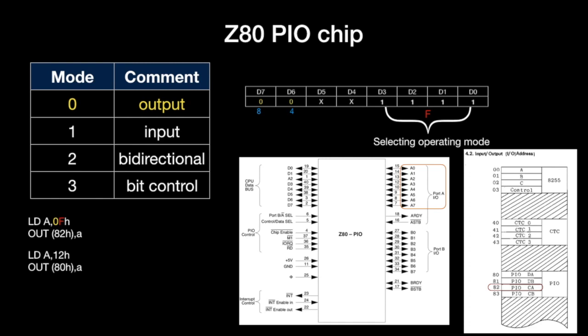After the value has been written, the ready signal goes from low to high, indicating that data is available for the connected device. Then the peripheral sets the strobe signal to low when it's reading the value from the PIO. And with the rising edge of the strobe signal, an interrupt is generated when enabled on the PIO. Finally, the PIO sets the ready signal to low.